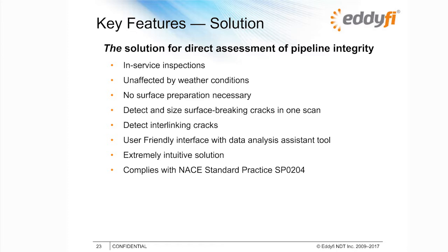It's very user-friendly with a dedicated interface and a data analysis assistant tool. So you can rapidly spot and measure the deepest point in a SCC colony, for example, using the different views. It's an extremely intuitive solution. Thanks to the software, it's easy to navigate and you can customize your display and suit it to your needs. And it complies as well with the NACE standard practice SP0204.